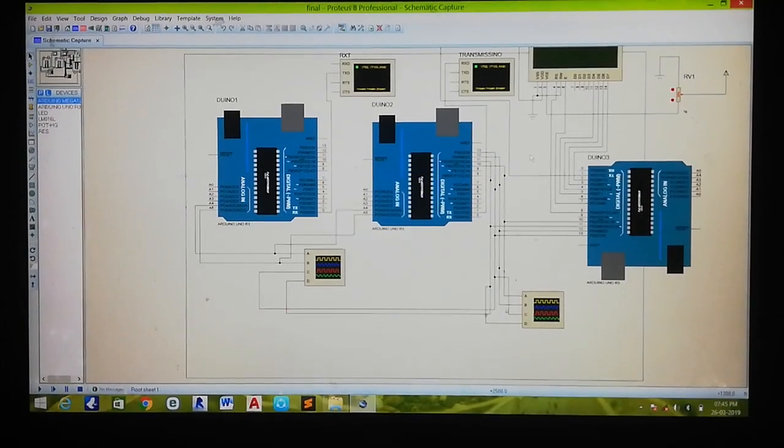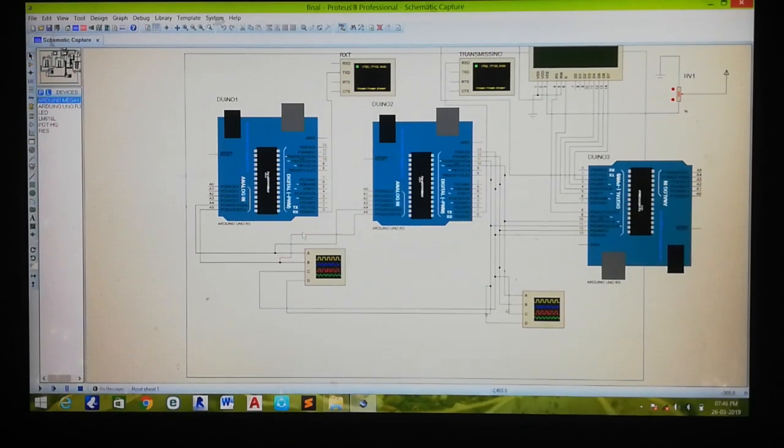Yeah, here we go. This is batch 11, and now we are going to see the protocol transfers between I2C and SPI. The I2C protocol uses two wires, SDA and SCL, data and a clock, whereas the SPI protocol requires four wires: MISO, MOSI, SCK (the clock), and a chip select. So these are the things actually.